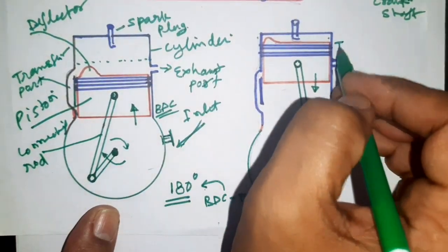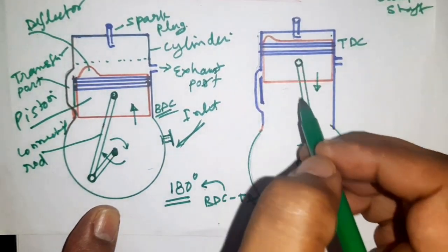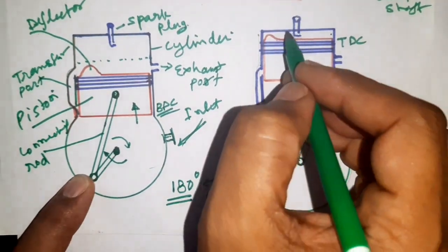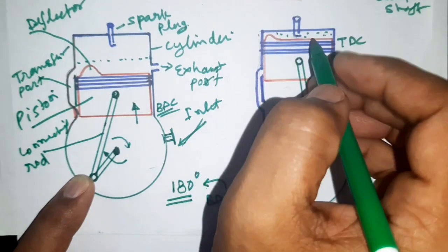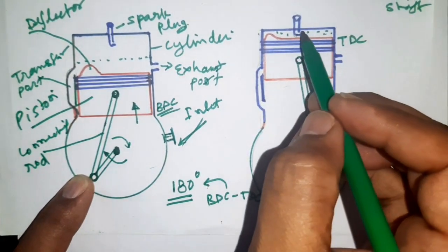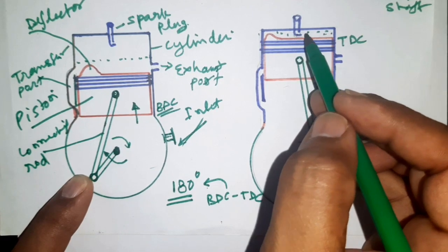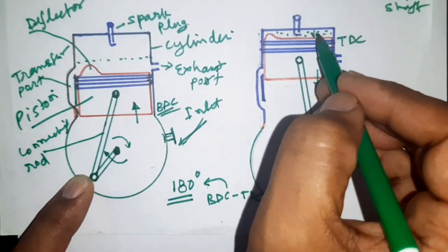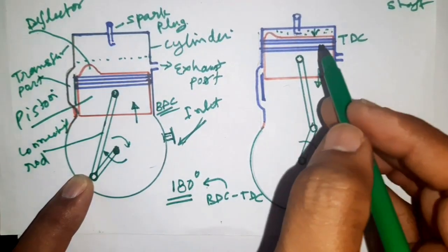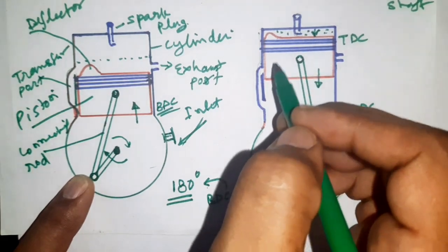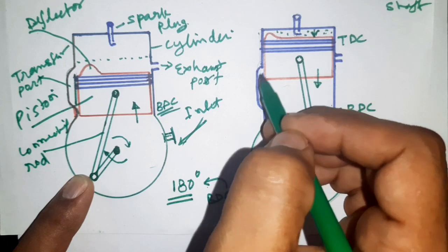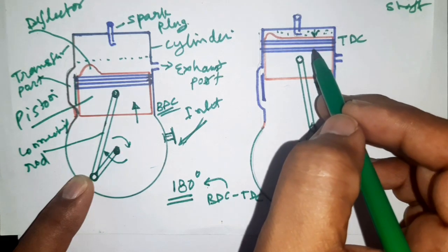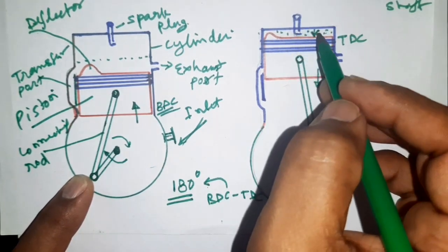this piston is at TDC, and it is going vertically downward, towards BDC. Here you can see the air-fuel mixture is fully compressed, and sparking is provided to initiate the combustion of the fuel. This combustion will push the piston in the vertically downward direction, meaning thrust is provided to the piston. Here you can see the bypass port and the exhaust port are both closed, so expansion is taking place in this top location.